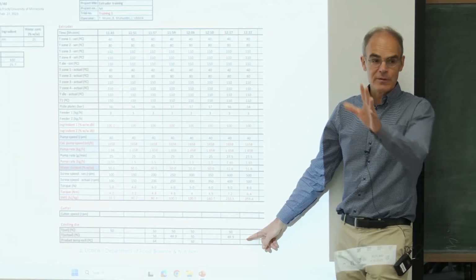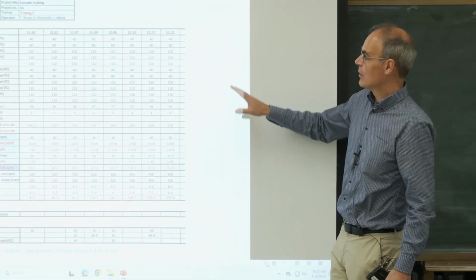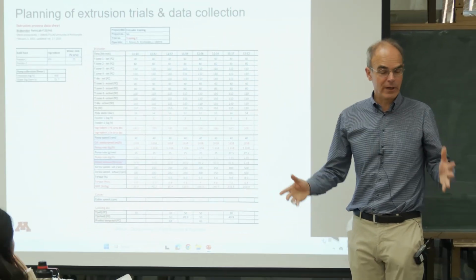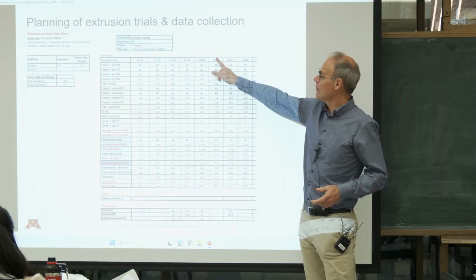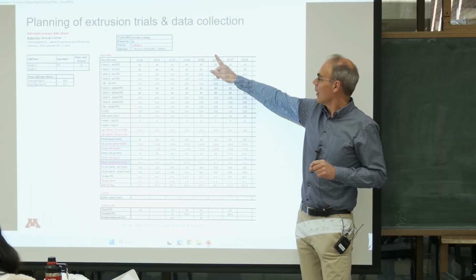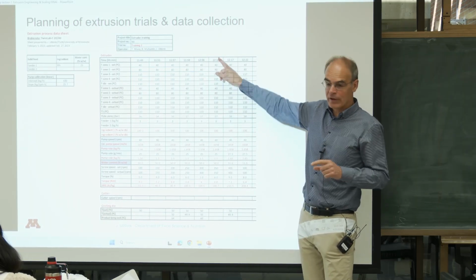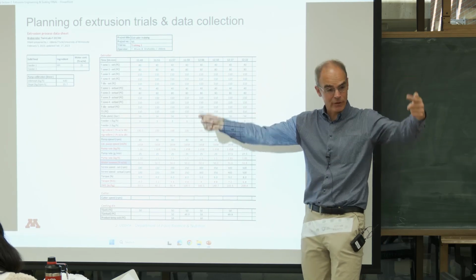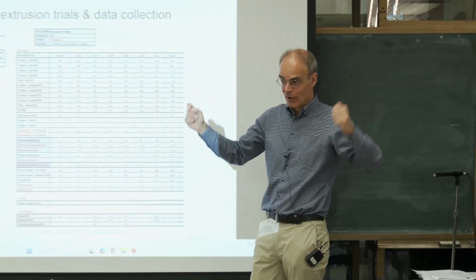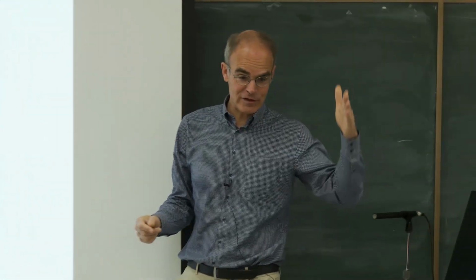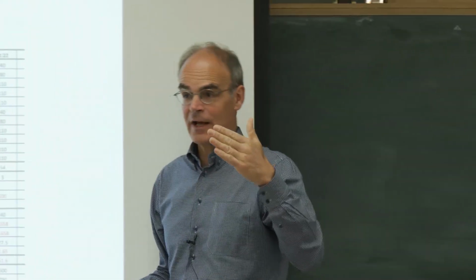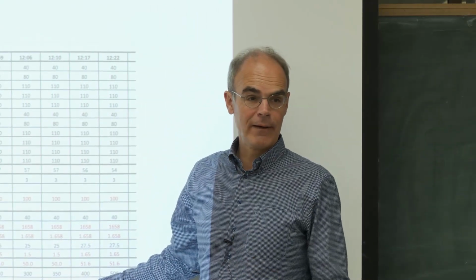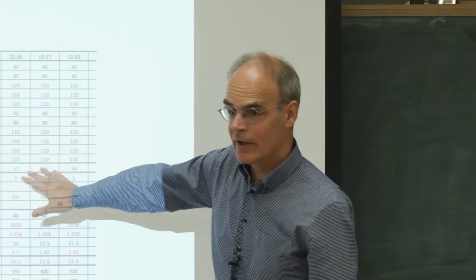Yeah. So we'll be sharing this sheet. If you're doing an extrusion trial, it's really useful to work with that and keep track of what you're doing, collect your data, and also really be able to connect your time point here to your actual sample. So you can do that later on the real analysis, because you can analyze all kinds of properties on these extruded materials. Like yesterday we did the swelling analysis, we did the anisotropy, today we'll do texture analysis, and it's for this sample. Yeah? Good, any questions on this?